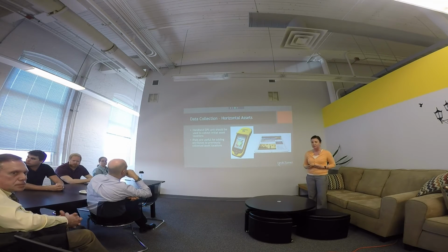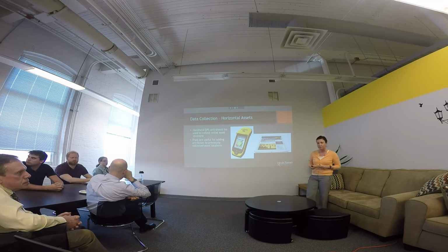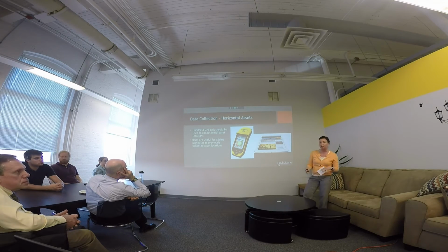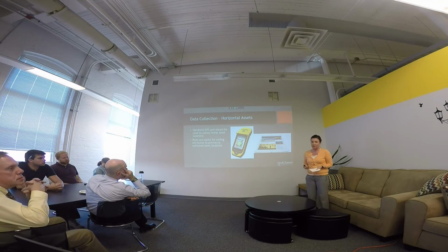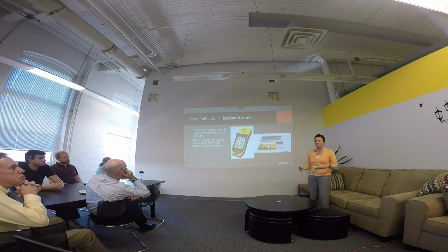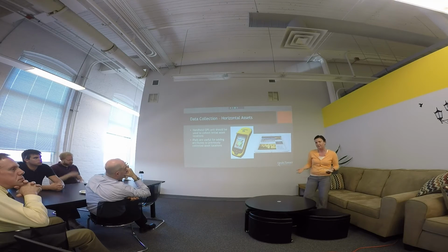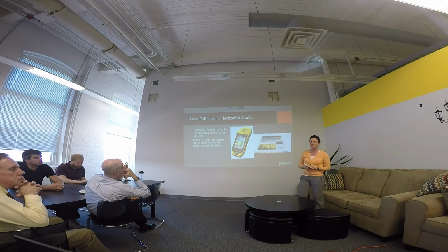But they told you in this case how close they wanted you to fix the hydrants? They didn't specifically say, but we're going to be using the GIS. Basically, we wanted it to be as accurate as possible to help them, because with gate valves, there could be some every 15 feet or less. So if we have 15-foot accuracy, that's not really helping them a lot.